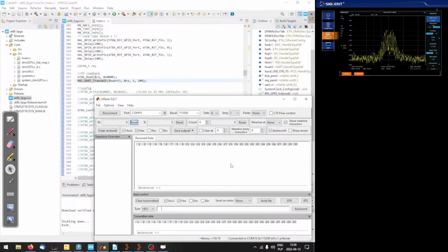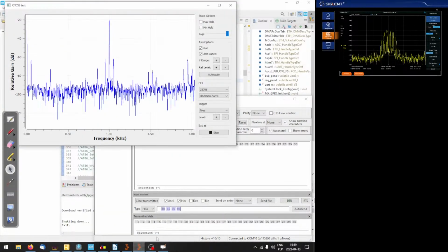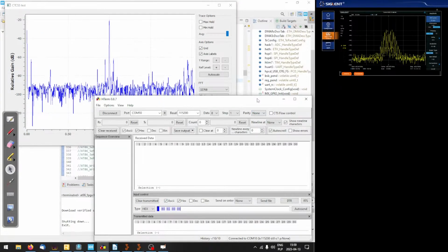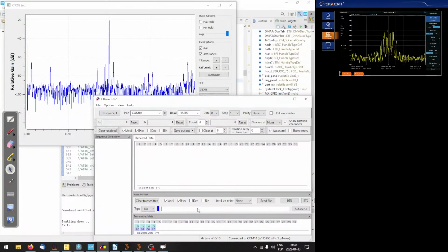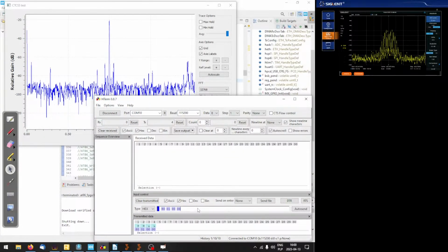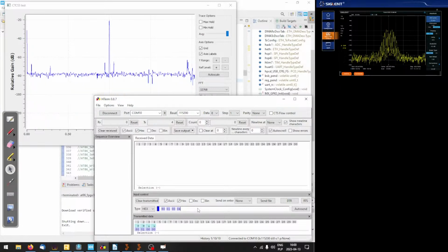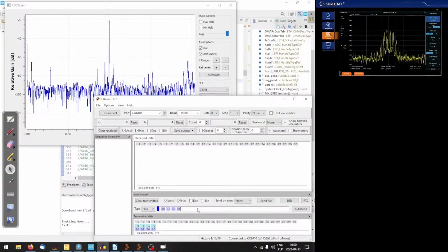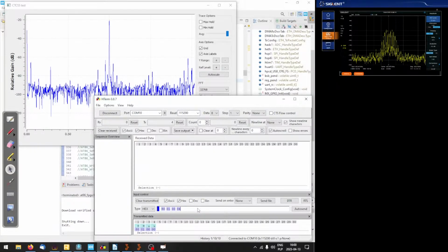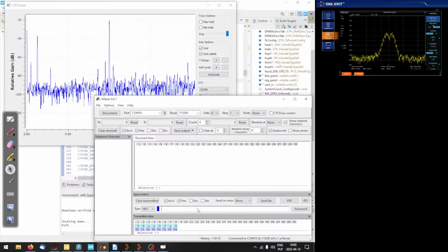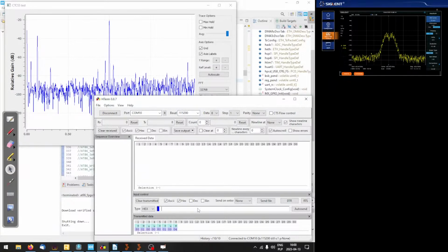All right, so back to the CTCSS. Let's clear this. We don't need it. Let's proceed with writing value of 0 to register 1, and that should change nothing in the spectrum. So we should still be seeing the same peak. Yeah, no CTCSS. All right, as expected. Now let's try and write a value of 4. That should give us a peak at 127.3, and the Baofeng should still remain silent. Yeah, there's the peak, and Baofeng is quiet.